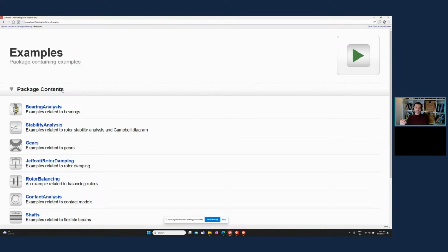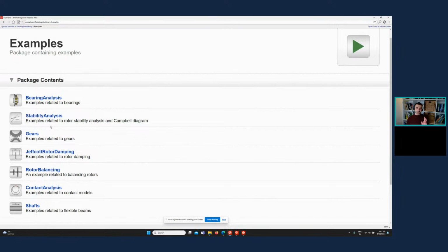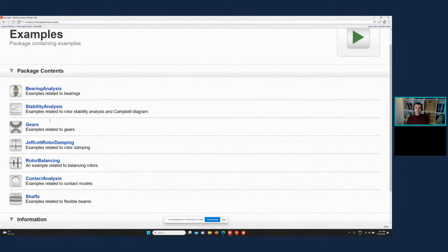But before doing that, you need to be sure about whether you are crossing the whirling frequency. I guess simulating this is cheaper than testing in real life. You can check whether the machinery survives at that new rotational speed.